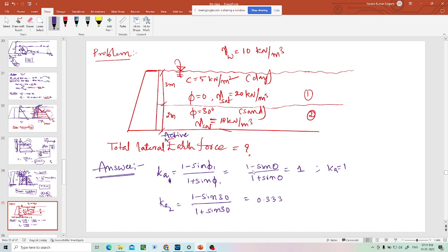Now we will enter into the vertical stresses. First, you need to find sigma V dash. Then you multiply Ka with sigma V dash. Then you might have to add or deduct 2c root Ka. So what is the formula?